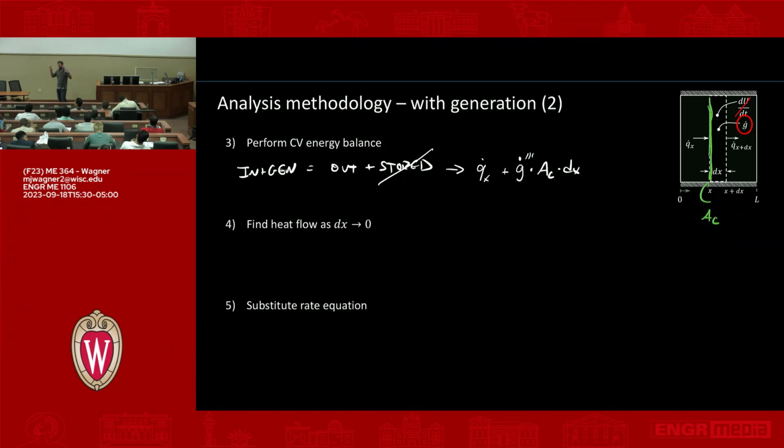If I contract everything down to a really small bottleneck and I'm trying to flow everything through that, the impedance goes way up, my resistance goes way up. So think of the cross-sectional area that's available in terms of that impedance model. That's the long answer. The short answer is yes. It is the area that's available as you're moving in the x direction. You see that there's a width into and out of the page in the z coordinate, and there's a height in the y coordinate. The cross-sectional area is that height in y times the depth in z.